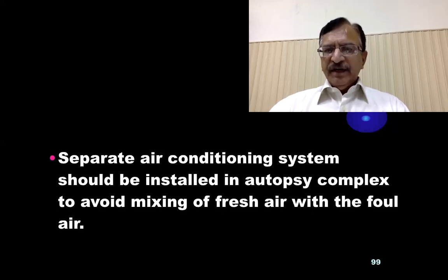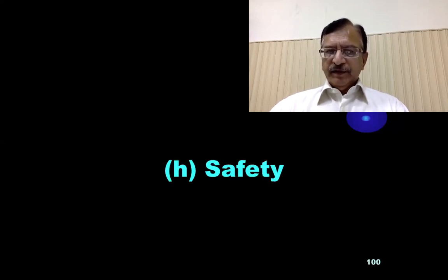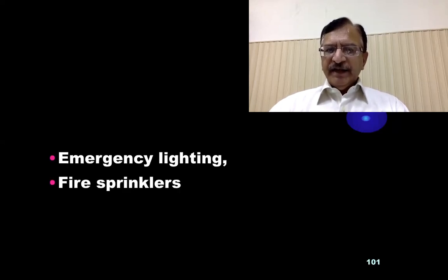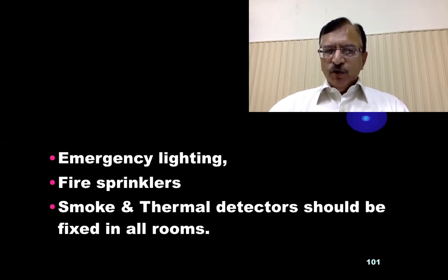Regarding the air conditioning, a separate air conditioning system should be installed in the autopsy complex to avoid mixing of fresh air with the foul air. Regarding the safety, emergency lighting, fire sprinklers, smoke and thermal detectors should be fixed in all the rooms.